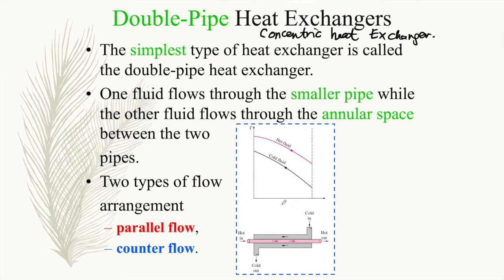As we can see in this figure, the cold fluid comes in here and goes out here. Hot in will be in the tubes. For the temperature, we have hot temperature here. For example, we insert 80 degrees Celsius of hot fluid, and we want to reduce it to 20 degrees Celsius. Your graph will be like this for the hot fluid, from high temperature to low temperature.